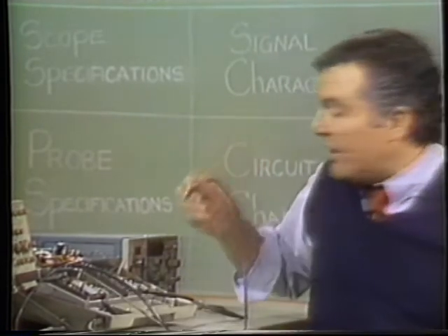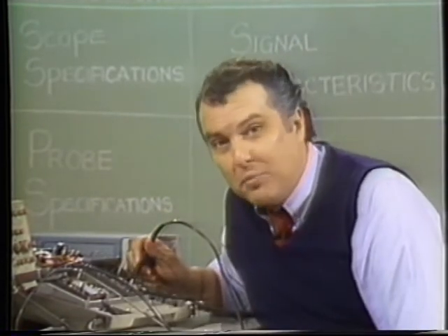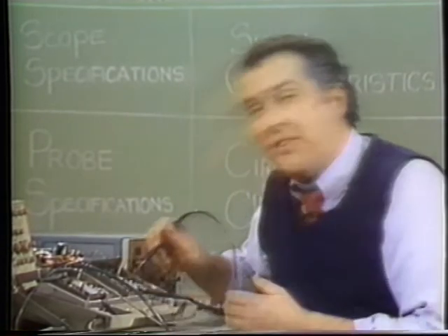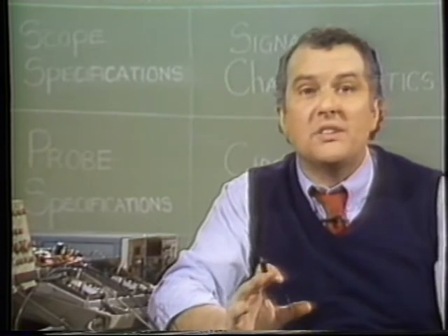Often the same signal will appear in many places on the circuit at the same time. For example, pick a transistor's emitter as a test point instead of its base. And if that isn't possible, you will need a probe with as high an Rin and as low a Cin as possible. You will need an active probe.